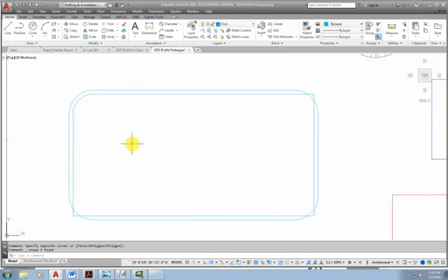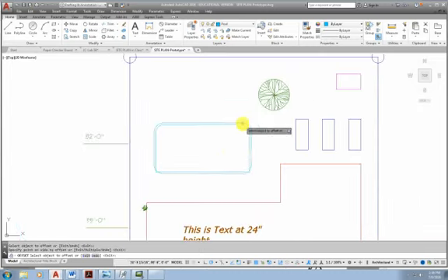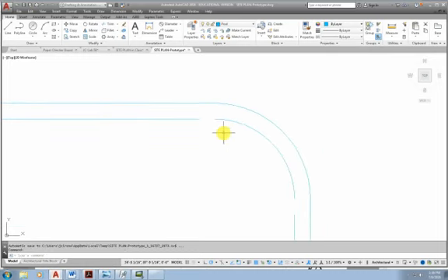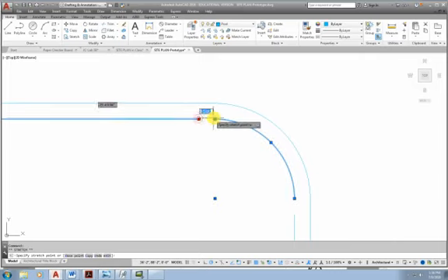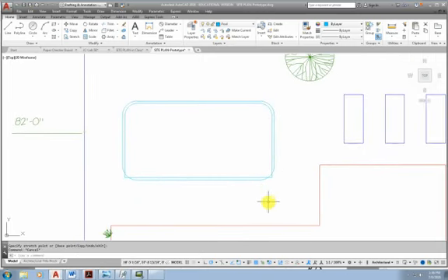But that's the kind of thing, versus if I was to go and fillet it with the 3 feet, which is still modal, it's not quite right. And so I'm going to delete that, and then I'm going to offset 6 inches. And then I can grip it. AutoCAD has some really nice things about it as far as working with these grips. I really like them for doing things like extending lines by making those grips hot.